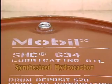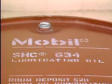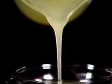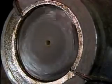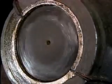This synthetic oil is called a synthesized hydrocarbon, or SHC. It's able to continue flowing at very low temperatures and to resist oxidation at very high temperatures. This is a sleeve bearing. It's simply a round cylinder that supports a shaft rotating inside it.